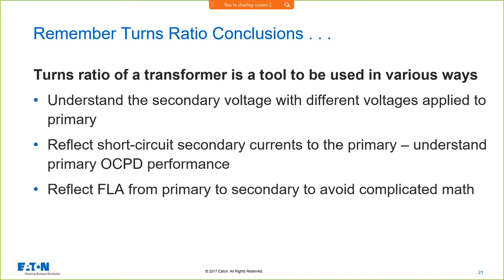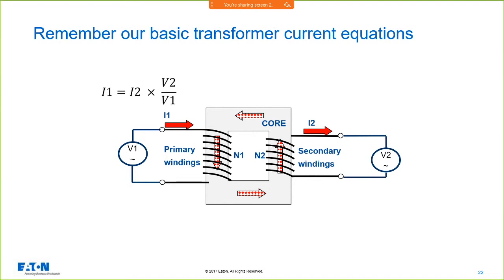So again, the turns ratio is a tool, and understanding those basic fundamental equations is important for a lot of different things. Understanding your taps, understanding short circuit currents on the secondary, reflecting currents from primary to secondary, things of that nature. You'll never know the application. Various applications will present themselves where, if you understand these principles, it'll make your life easier. So again, remember those basic equations.